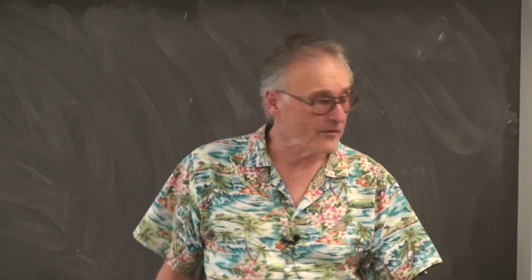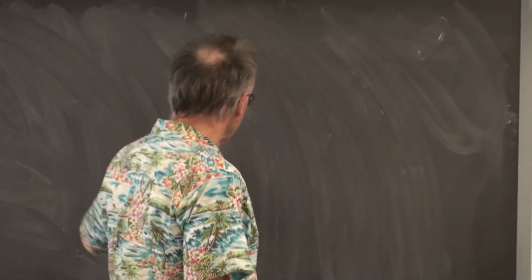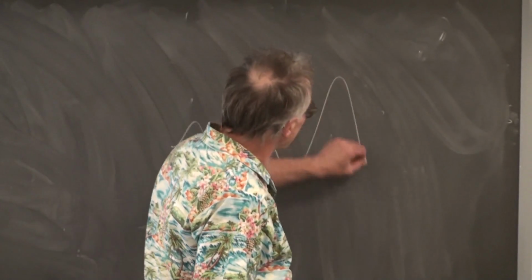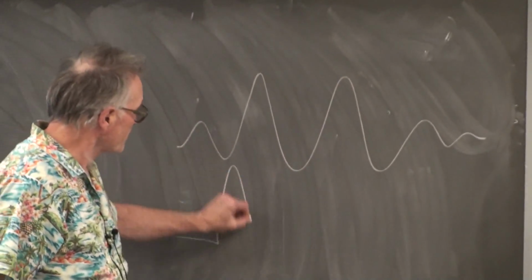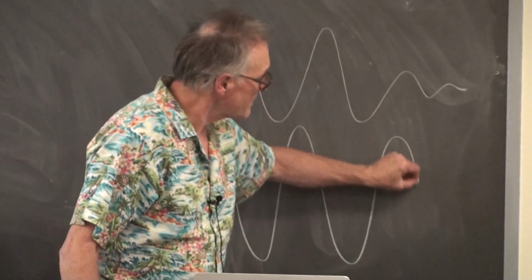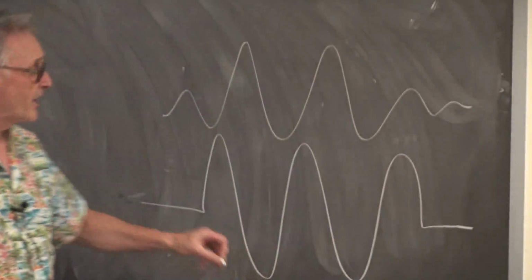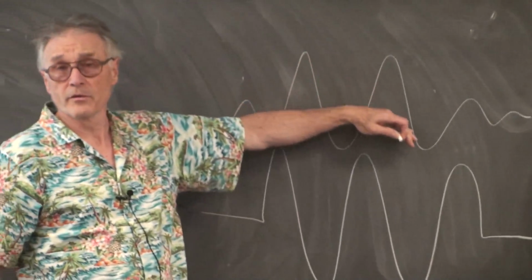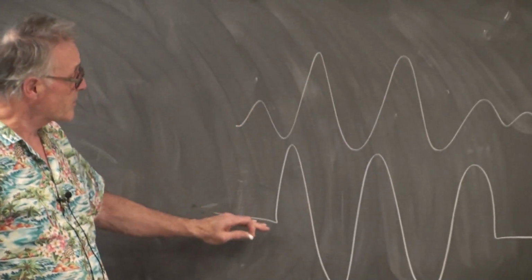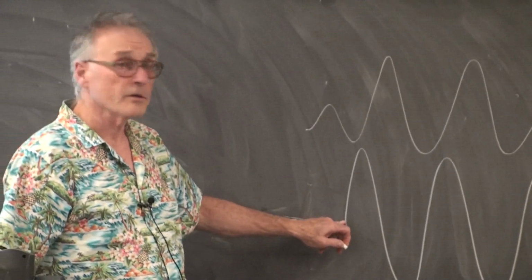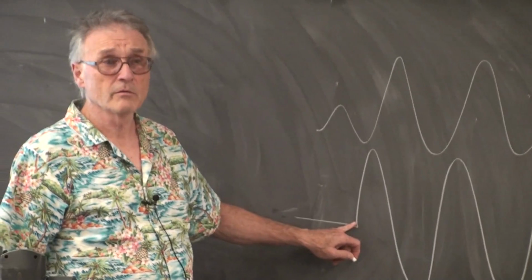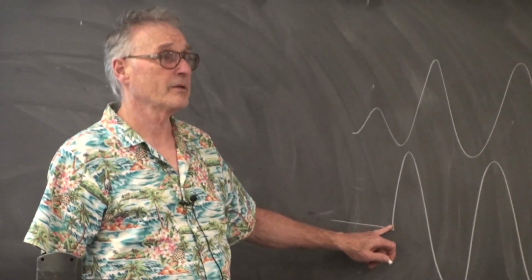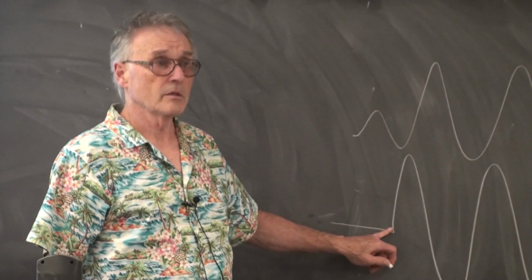The tone bursts have to ramp up, so the tone bursts are going to look like this rather than this. So you have to amplitude modulate the sine wave so that you avoid the corners here, because whenever you have a corner in a signal, you have broadband signal.